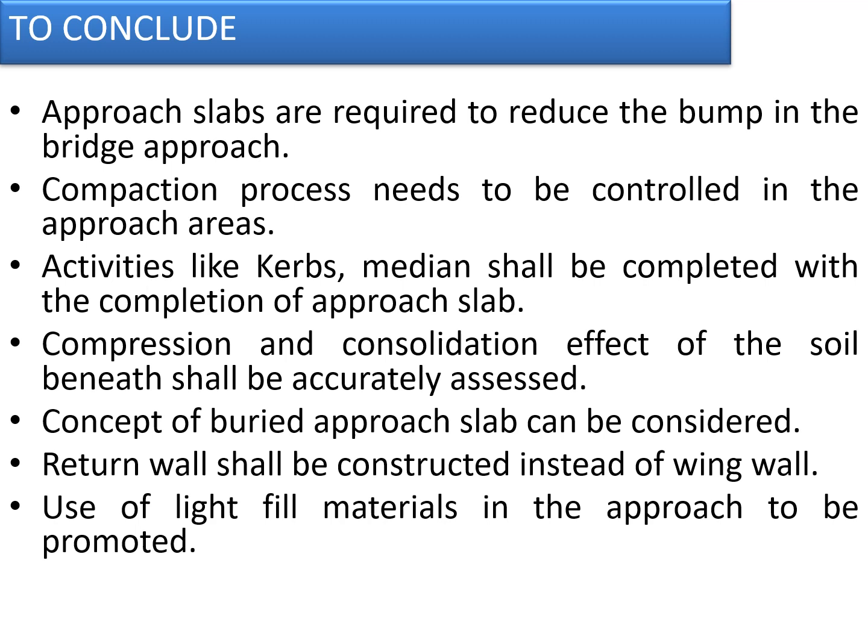Return walls shall be constructed instead of a wing wall, as the return walls generally create a confinement from all three sides, and the chances of erosion of soil due to the movement of the water will be minimum. Use of light fill materials in the approach slabs needs to be promoted, as the pre-compression or the consolidation of the fill materials will be minimum.